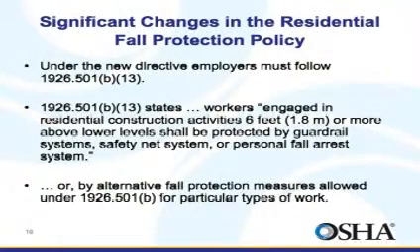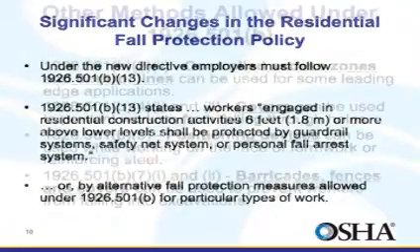Then they can use those systems as part of a written, site-specific fall protection plan that meets the requirements of 1926.502(k). More simply put, all employers performing residential construction must now comply with 29 CFR 1926.501(b)(13).